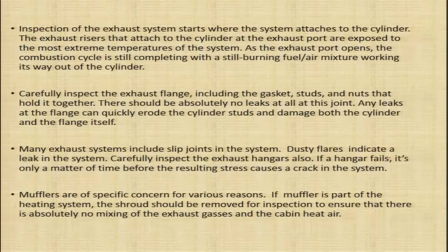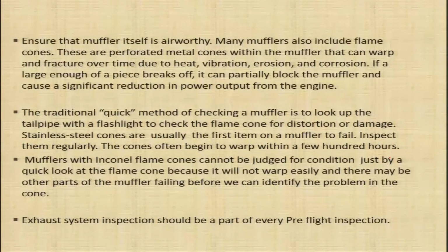In case the muffler is being used as part of the cabin heating system or as part of another heating system, the muffler shroud, the shroud over the muffler, should be removed for inspection, and it should be ensured that the exhaust gases and the cabin heat air are not mixing together, and everything in the muffler is working satisfactorily. Ensure that the muffler itself is airworthy.